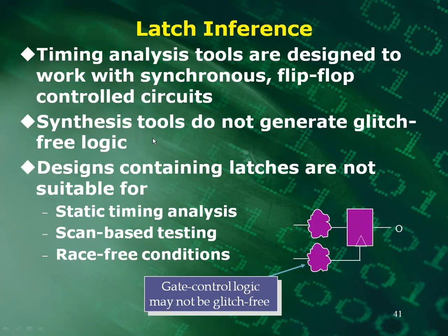And synthesis tools do not generate glitch-free logic. That's going to be up to you to realize what you're doing. Okay, what do I mean by glitch-free logic? Well, let's say that I had a flip-flop, and for the clock, it didn't just come from a particular clock source, but it came from some combinational logic of maybe a couple sources. Okay, you can get into a real problem here, and this is what's called a gated clock.